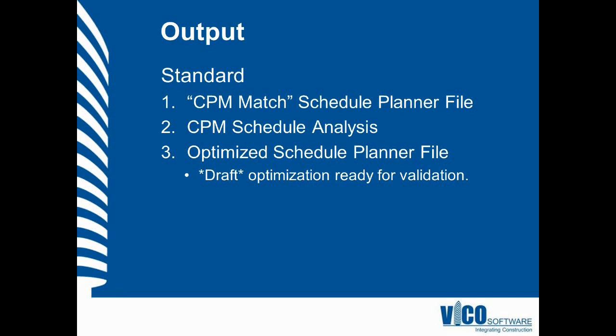We can use, following typical location-based management theory, to optimize the crew flow, eliminate starts and stops, balance resources, etc., and provide a draft-optimized schedule that we could then carry over into some validation workshops where we will come to your office or come to the job site. We'll first review the CPM match and then work through the optimized version with you and your subcontractors to validate the data and to hopefully get some sign-off and approval and rollout.